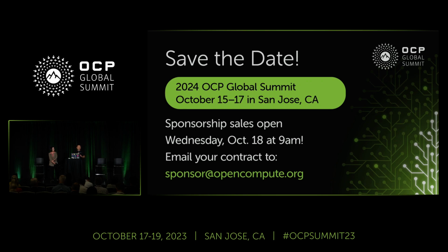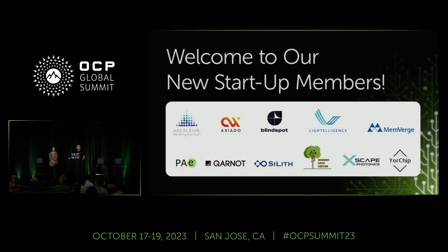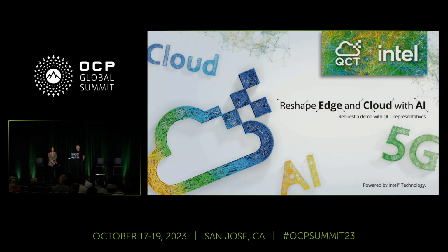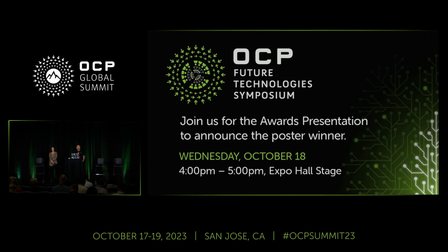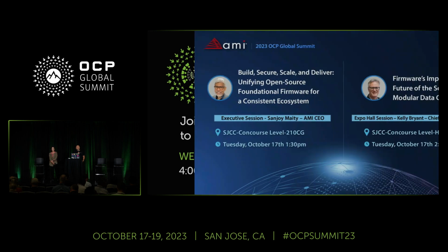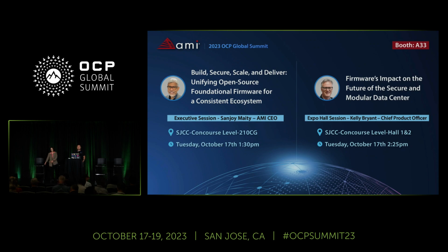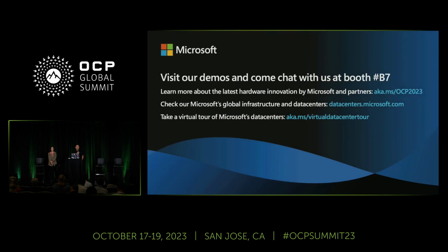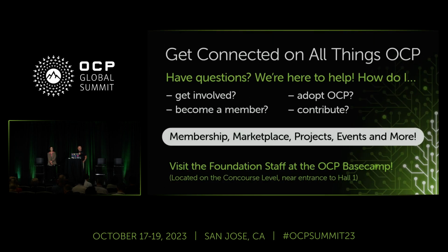But assuming every vendor or every design is done in a sensible way, we still think TDECQ is a useful metric. It doesn't mean it's the only metric, but it's still a useful reference. Did you find that usually the best TDECQ corresponded to the best bit error rate? Like I said, it's probably not correlated in all the cases, but trend-wise, they can still be correlated.